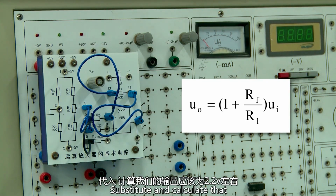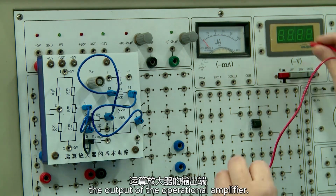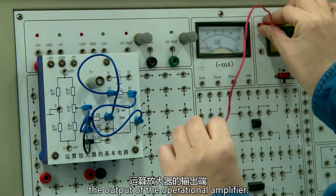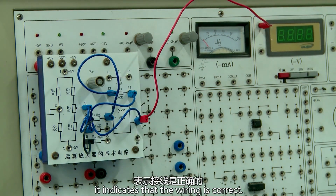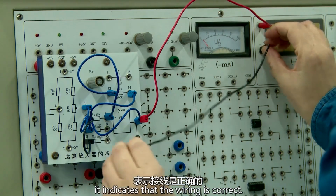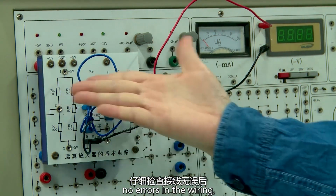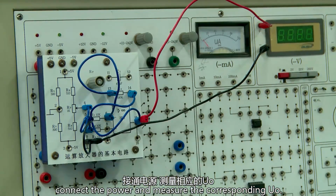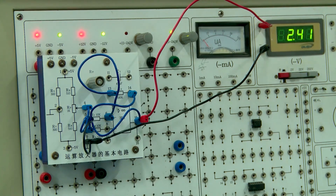Substitute and calculate that our output should be around 2.2 V. We connect the digital voltmeter to the output of the operational amplifier. If the output is correct, it indicates that the wiring is correct. After carefully checking that there are no errors in the wiring, connect the power and measure the corresponding UO. The experimental data is correct.